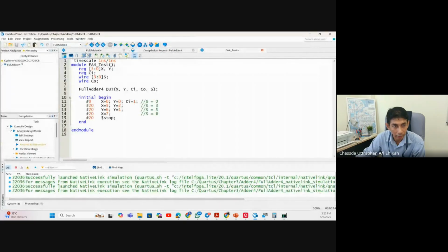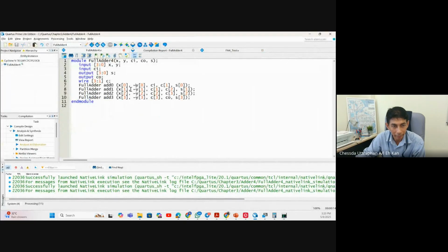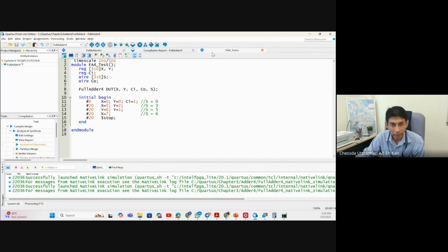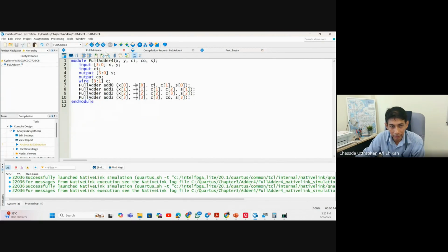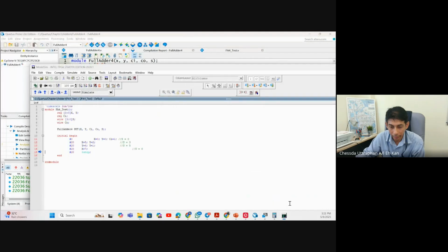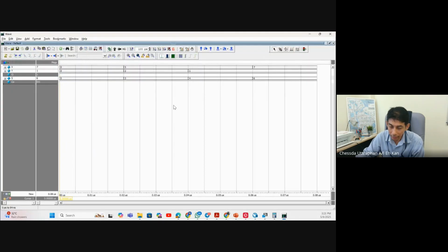Yes, adder. This is adder, right? But we change this to not y to get the first complement. And then Ci equal to 1 to add 1 to get the second complement. And we have the subtractor already. And this is what is in your computer.